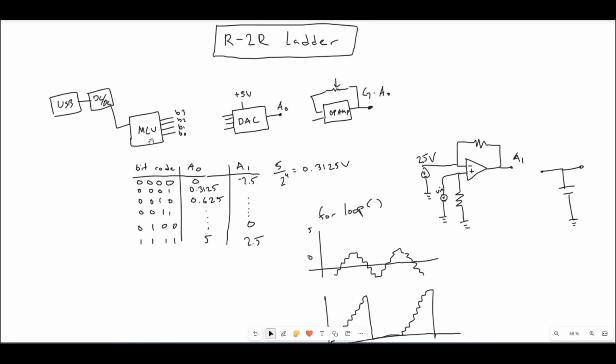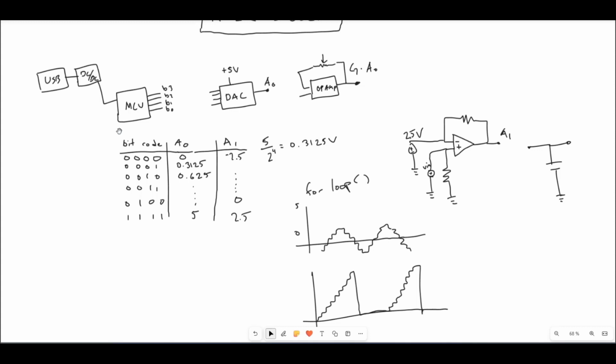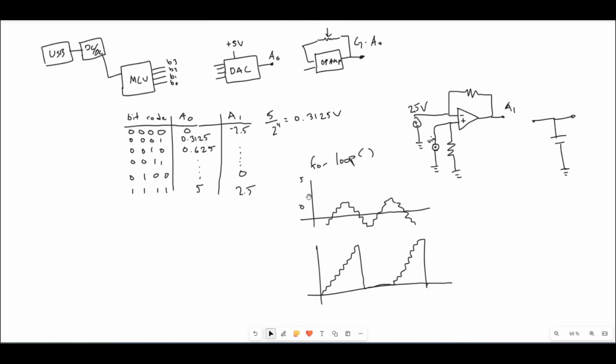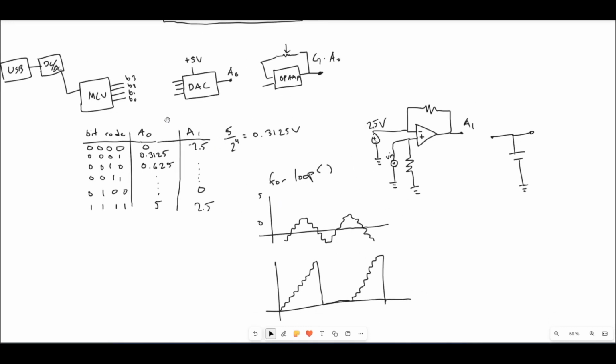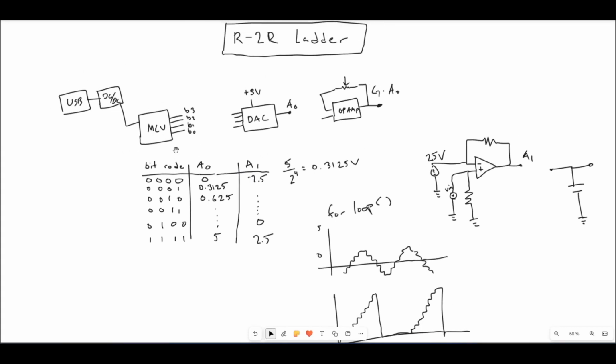So you're going to have to go into each register and toggle the bits there to get everything set up. Then you would have to create your own functions. I guess you can create your own header file, create all the waveforms, and import those in your main loop, and have some sort of super loop.